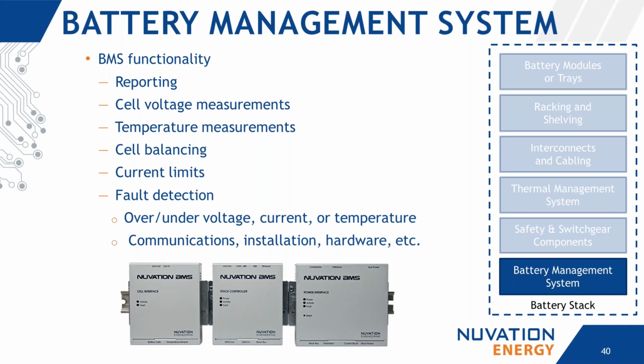And finally, the BMS is able to detect faults within the system. This includes faults such as over and under voltage, current, or temperature, and can be either at the stack or at the cell level. It also has the ability to detect faults that may be due to communication, installation, or hardware, which can be very helpful when commissioning a system to have more insight where things may not be correct.